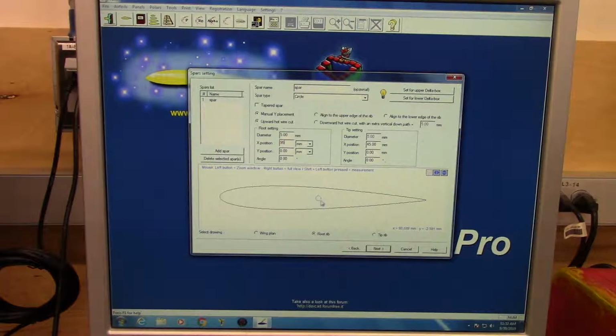And now that I have that plugged in, it does move it farther back on my wing. It's no longer the thickest portion, but this airfoil is larger, so it should be able to handle that. And if I look at my wing plan, that gives me a nice straight spar cut through my panel, so that I could have a spar that travels both through this panel and through a symmetrical one on the opposite side.